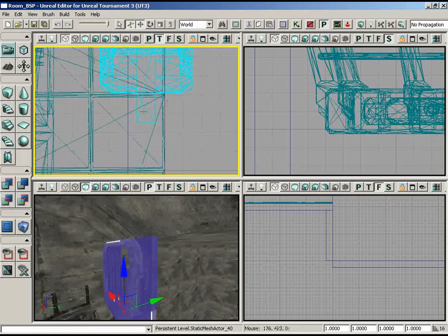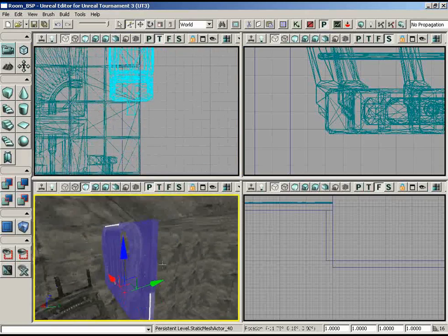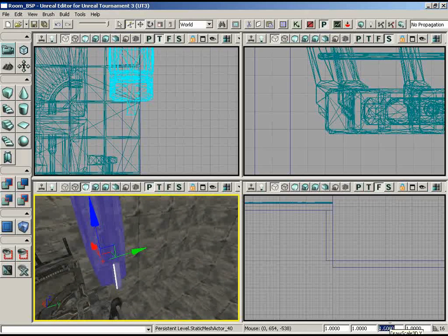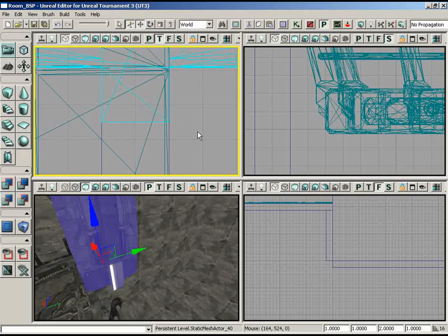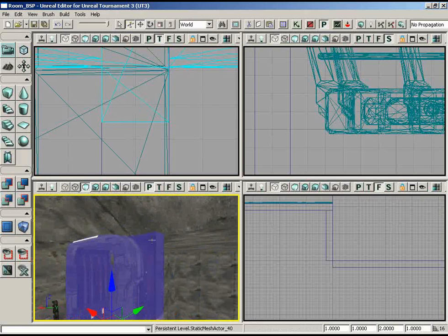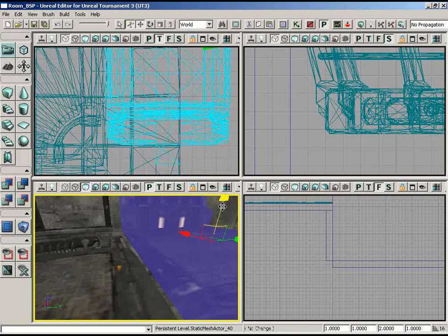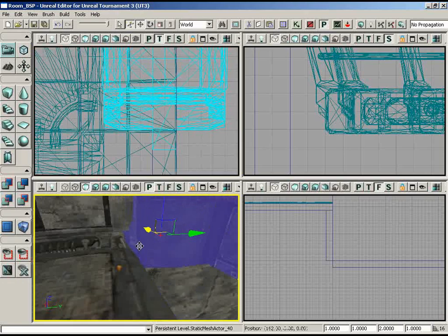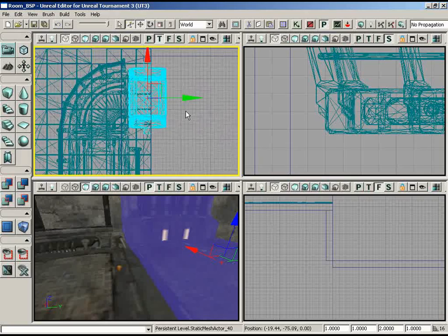But at the current scale, it's a little bit too narrow. As a matter of fact, it looks like it's about half the width of that other brush. So we could take this entire doorway and scale it out in Y and draw a scale 3D, maybe even by scale 2. And then if we zoom in, you can see that fills up the 32 space. So if we start with this as a reference, we'll end up with a wall that's 32 units in thickness. So now let me move it around just a little bit to get it lined up with the floor here. Move it down just a little bit, and I didn't mean to grab the manipulator, I meant to grab the viewport, but that's okay. We'll snap this back in,